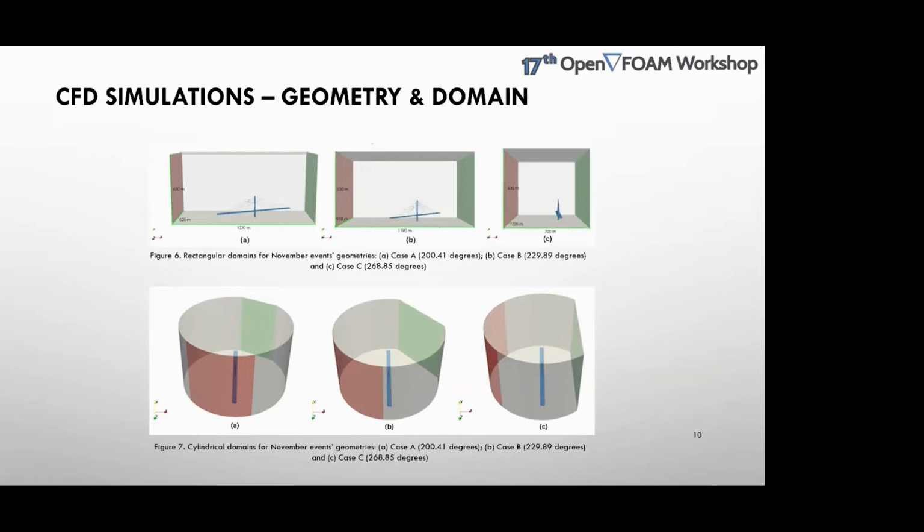The radius of the domain is 500 meters to ensure that under most of the angles, there is enough space between the geometry and the outline to let the flow fully develop. And you can also see that the inlet face is a plane rather than an arc face, just because I want to avoid the interlacement of the incoming flows. And the size of the inlet face is also set based on the equivalent length of the bridge under the certain yaw angles.